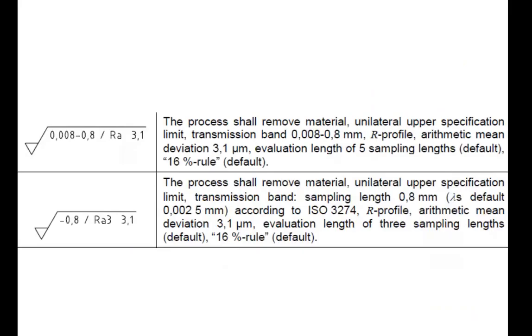If over the surface the pattern is entirely the same, and with the naked eye it is not possible to distinguish any change in the surface quality, then the standard says that at the inspection stage, first randomly select a place over the surface, and over there, define a path, and then along the path, move the probe.